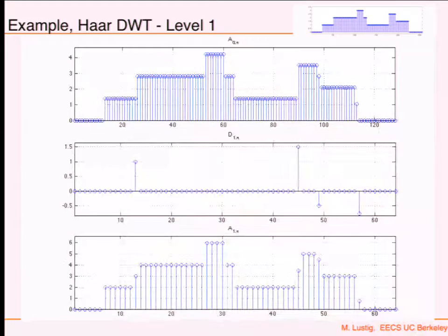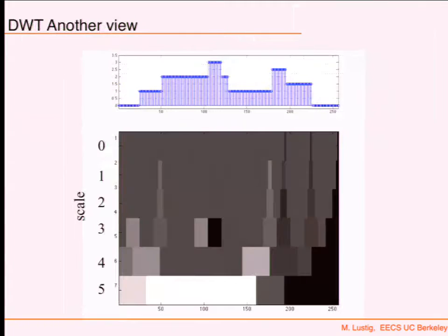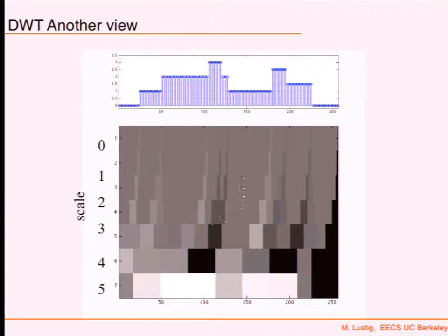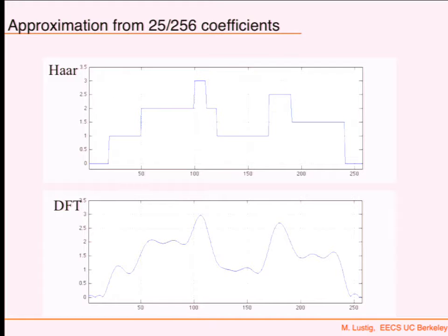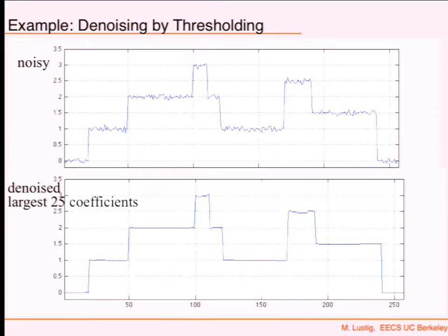The application, I went over this last time, of how you do this decomposition, and you get this really nice view of the space of time frequency through these ridges, a kind of zoomed out version of your signal. So detailed as you zoom in and then zoom out. But what's really interesting is how it makes signals sparse. And sparsity can be used either to denoise, like in this case, or for compression, if you just store the largest coefficients. And as it turns out, JPEG 2000 and all the recent video compression, like Skype and things like this, all use wavelets. Okay, and then for compression.